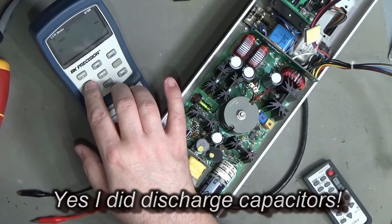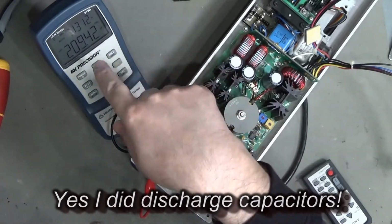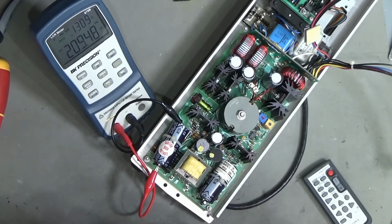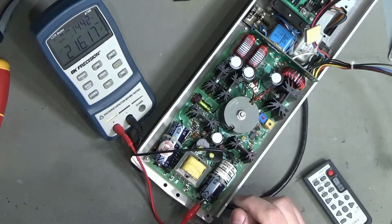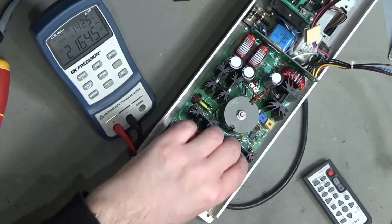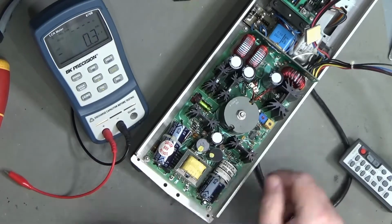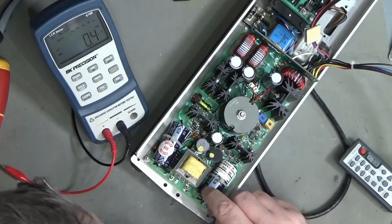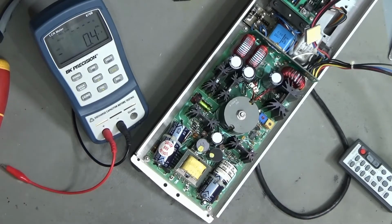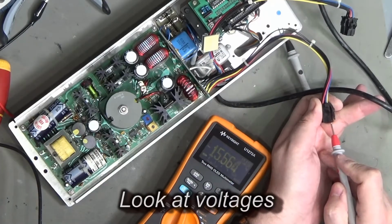Okay, so on ESR, thank you very much. So 209 microfarads, 0.13 ohms ESR. So no problem there. 216 microfarads and 0.14 ohms. So again, pretty happy with that. Can't complain about that really. So 85C, 200 volt, 200 microfarad. They're looking good. Bugger. So blue, minus 15.